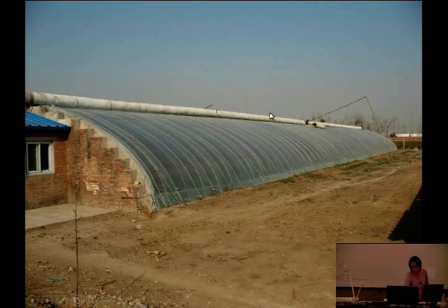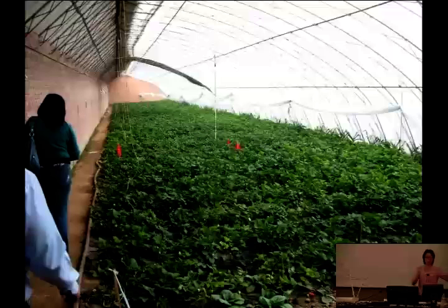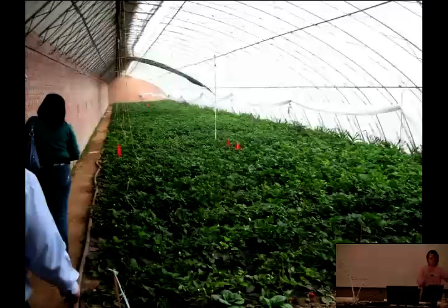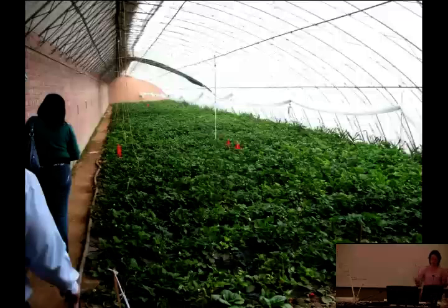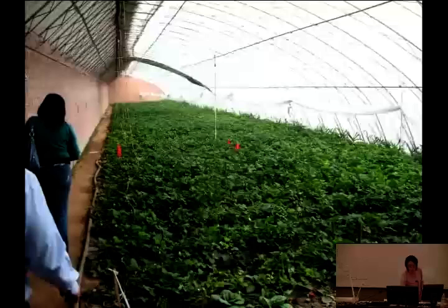And there is some kind of insulation material, because they use this greenhouse in wintertime for season extension. The north side is always a very thick wall as a heat sink. The heat is stored during the day in that wall, and also in the ground. That warms up the inside temperature many degrees higher than outside. So it's a very low-cost, sustainable, low-level production system.